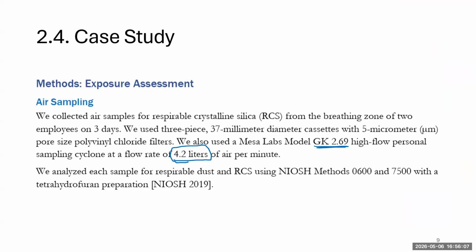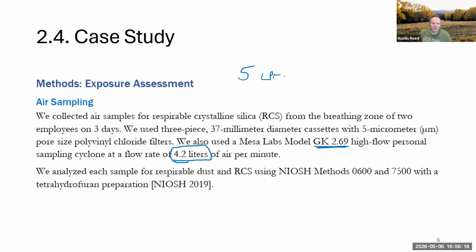I have not sampled at 8 liters per minute with a personal sampling pump. So I'll be honest, I don't know how to answer your question exactly. I think most are good up to 5. I might be wrong, but most of the common, top of the line pumps will do that. At 8, I really don't know. I'll have to dig to answer your question, but I think most should be able to handle 5.